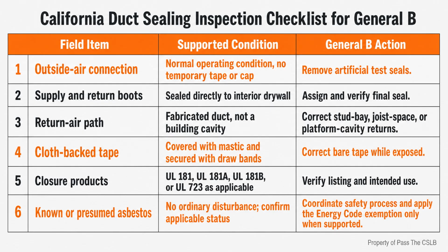The same principle applies to boots and plenums. I look for a continuous sealed boundary, not a collection of materials that merely looks finished from the floor. A neat joint can still be incomplete if the required closure system is missing a component.